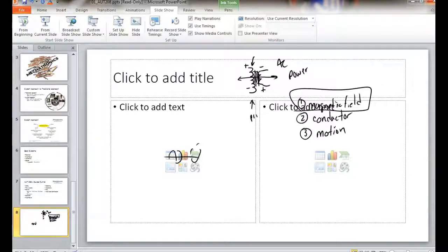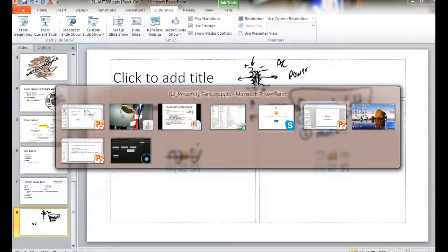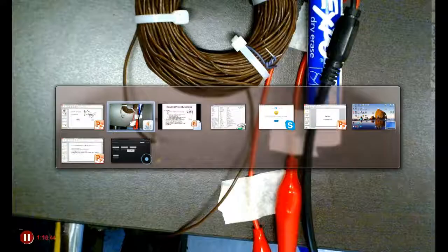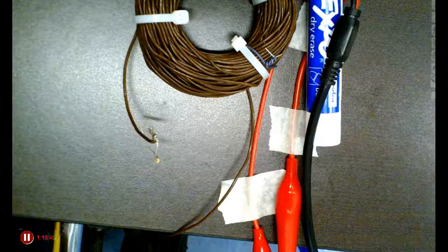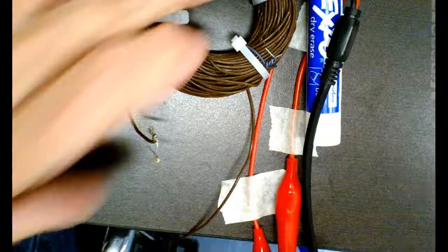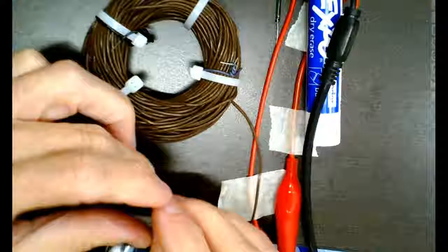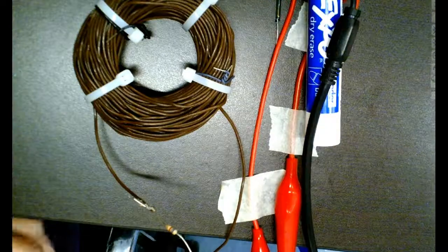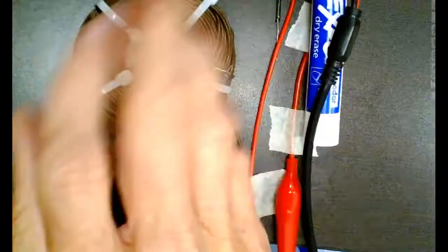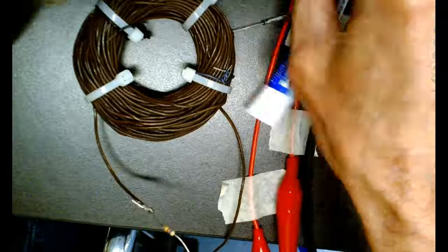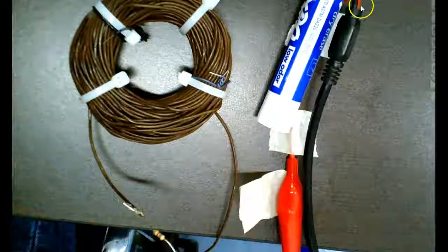So what we're going to have to do here is put a resistor in series with it, so I can measure the voltage drop across this. So let's see if we can do the same thing. I'm going to disconnect my capacitor, and take my function generator off, and I'm going to put it across the wire.